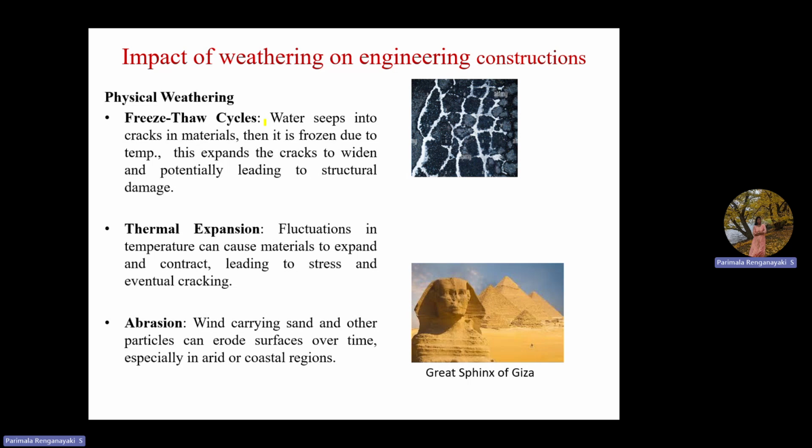Same thing we saw previously in the rock, but how is the same weathering going to affect the construction? Water seeps into the cracks in minerals. Then it is frozen due to temperature. This expands the cracks to widen, potentially leading to structural damage.